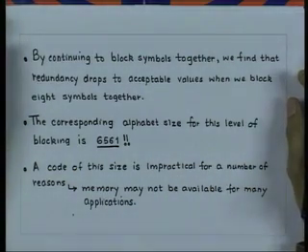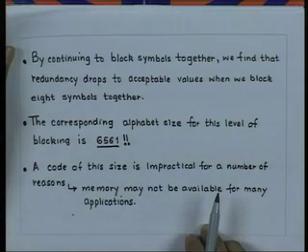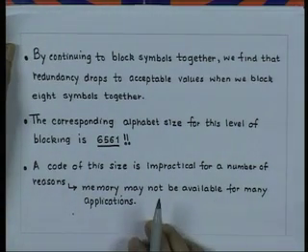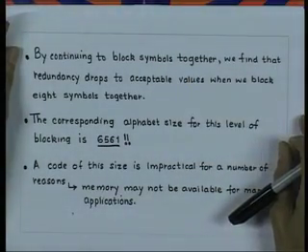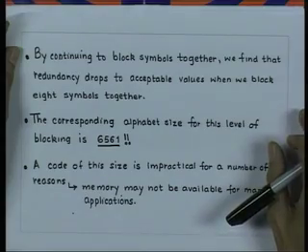First of all, memory may not be available for many applications. Now, even if it were possible to design reasonably efficient encoders, decoding a Huffman code of this size would be highly inefficient and time consuming. Next reason for not using this kind of code is if there were some perturbations in the source model, then we would have a major impact on the efficiency of the code.